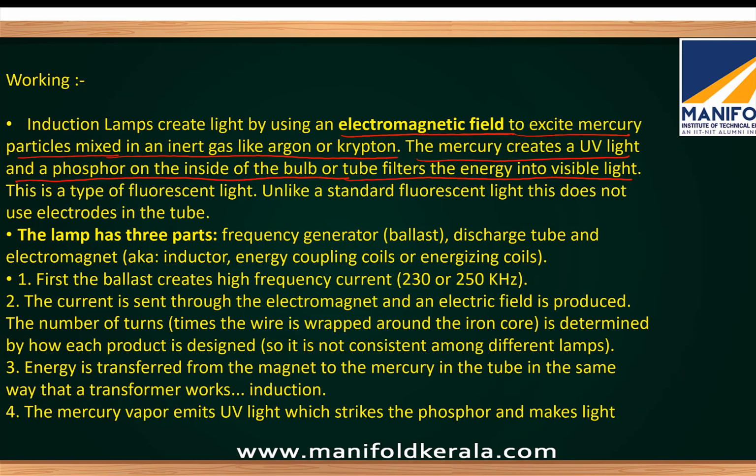Okay, so induction lamps work on which principle? Induction principle, and light is created by an electromagnetic field which excites the mercury particles which are in combination with some inert gas like argon or krypton. This mercury creates ultraviolet light, and the phosphorus on the surface of the walls converts this energy into visible light. Again, it's a type of fluorescent light.